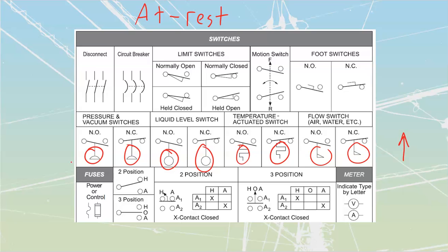And so during activation, the operator is always going to get pressed in the upward direction. In other words, for this pressure switch over here, it's a normally open pressure switch. I see that it's a disconnected line over here. On an increase in pressure, it is going to close. This one here is a normally closed pressure switch, which means that on an increase or an upward direction of pressure, this thing would then open up.